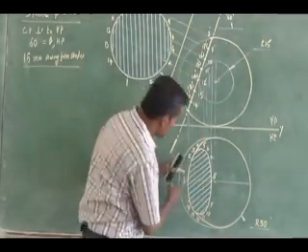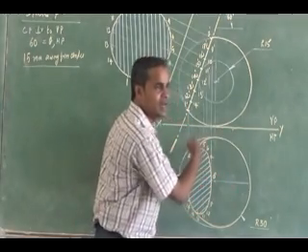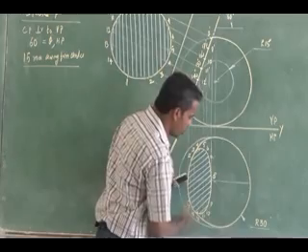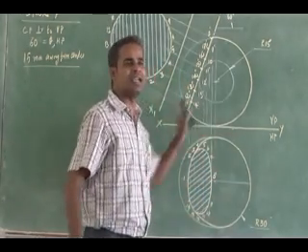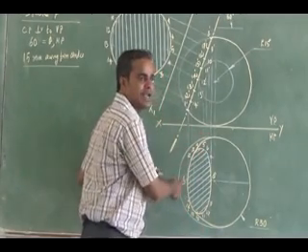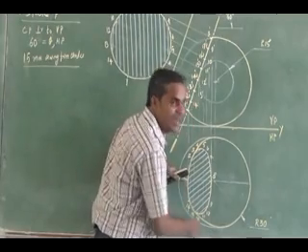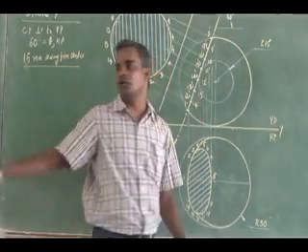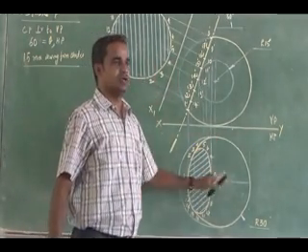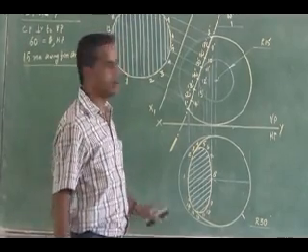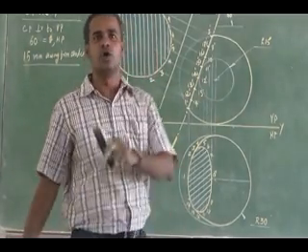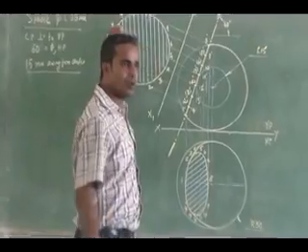Okay, the retained sphere. From 1, including the apparent section, tangent to that, to the top view, you have to connect it. So that is going to be your retained portion. So this is the actual top view. So from the cutting point 1, tangent to that apparent shape, you have to connect it to the original top view. So this is going to be your retained sectional top view of the sphere. Right? So the final front view retained portion you darken it. Then you hatch the true shape of section, erasing the projector lines.